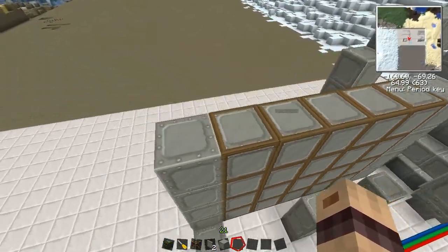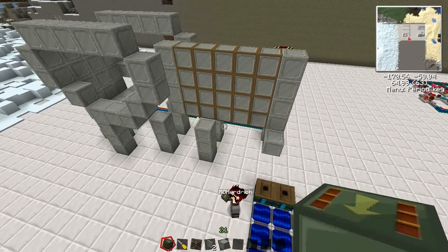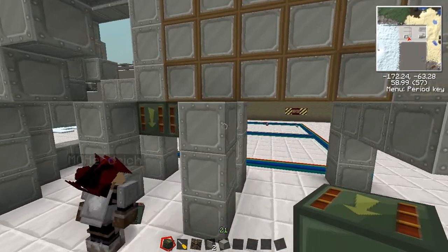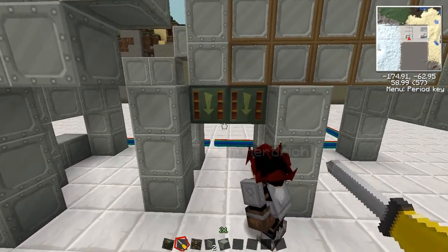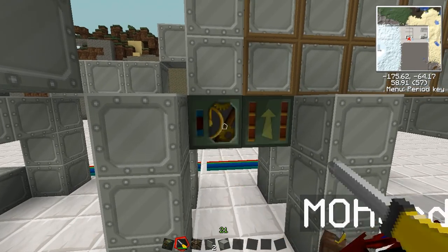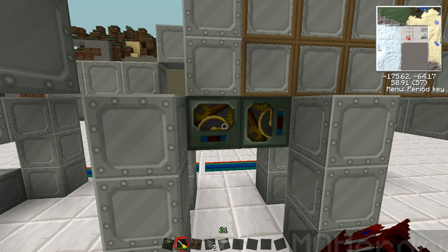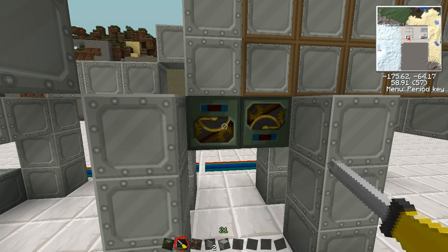So how do we move these frames, Mark? We use these nifty little motors here. I'm holding an end, and you do now as well. And we place them here and here. We get a handy screwdriver out. And when you right click it, you can rotate them. And when you hold shift while clicking them, like I'm doing, you rotate them on the other axis. So shift right click, like I'm doing at the moment, will roll the entire motor in a certain direction.